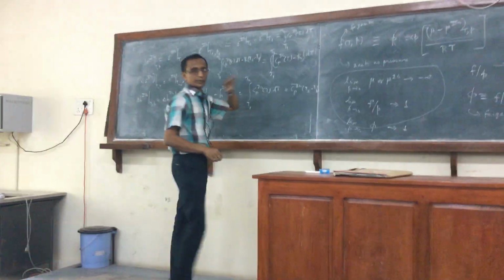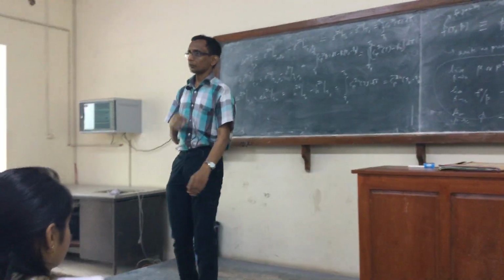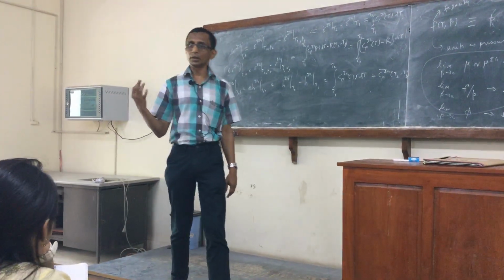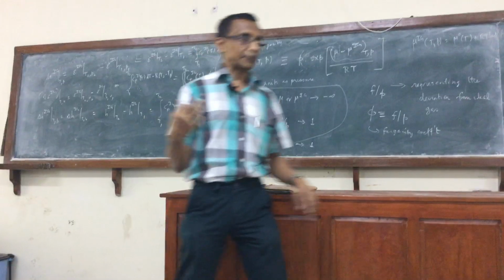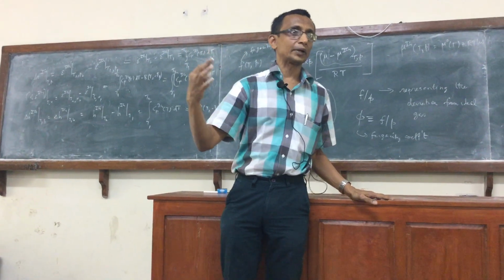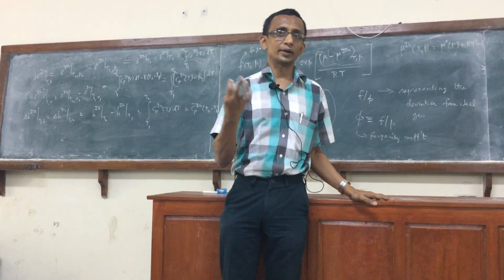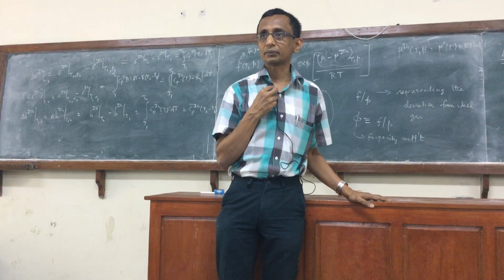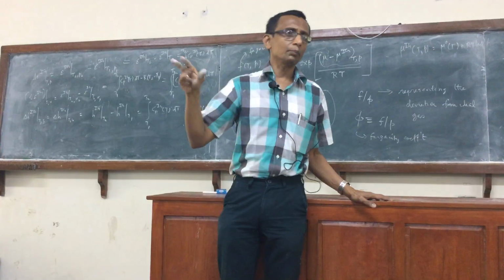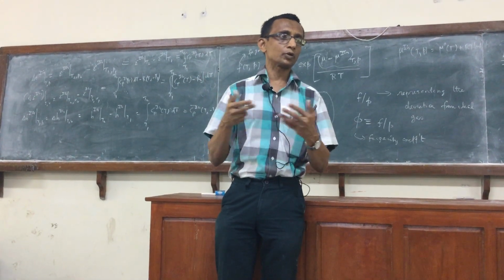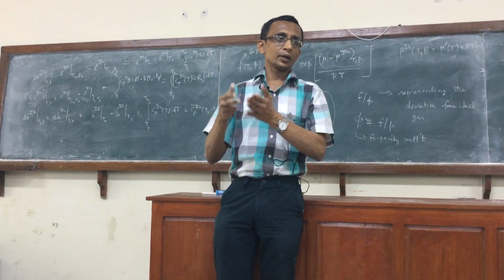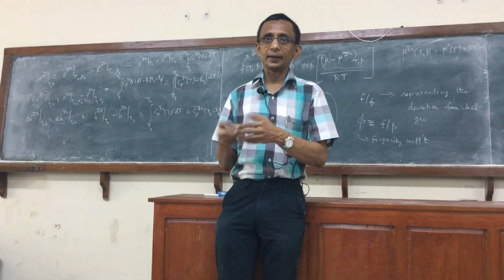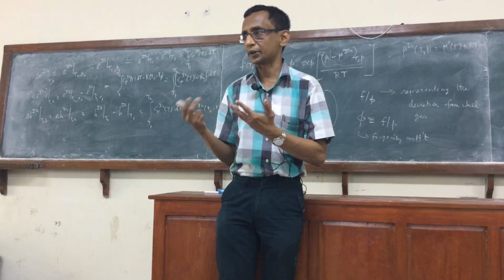Similarly you can write this also in a similar way, but that is a special case where there is not a significant change in the specific heat over the temperature range I am interested in, right? Over a few hundred degrees, it might not vary that much. You have to check that. Then I can replace it by some average value, or a good approximation could be I calculate the Cp at T1 and at T2, take the arithmetic average, let's say, and then use that as some approximate. This is only an approximation.